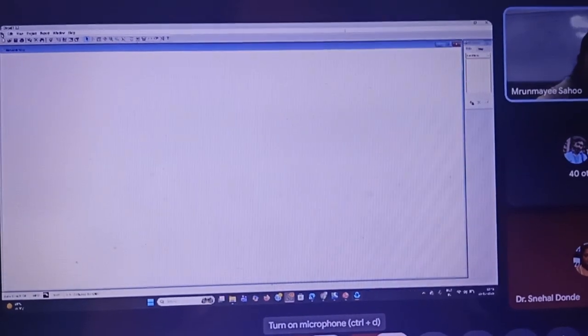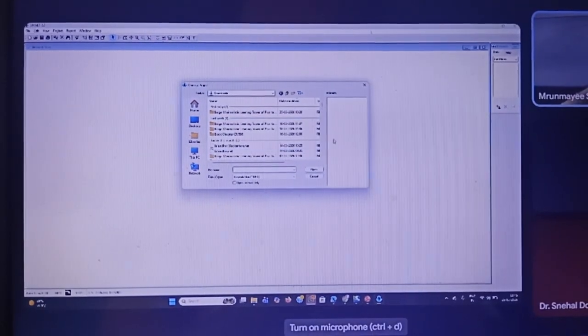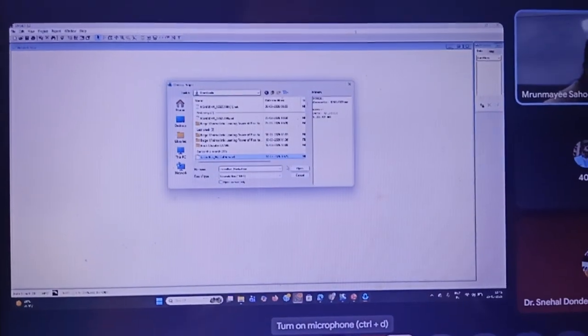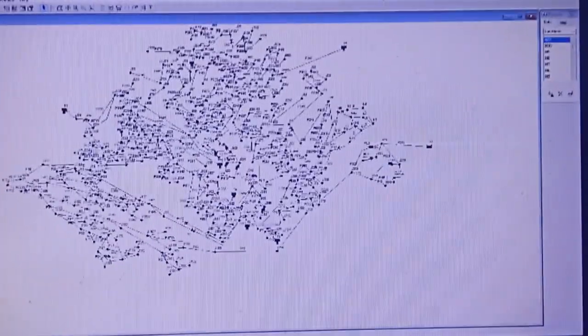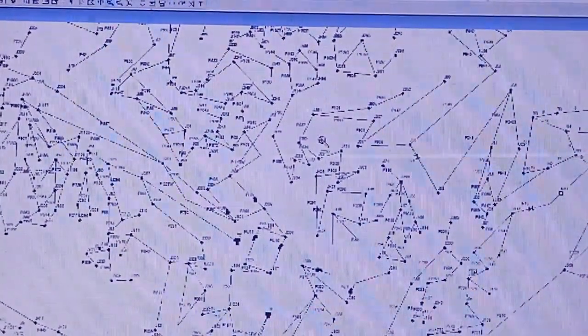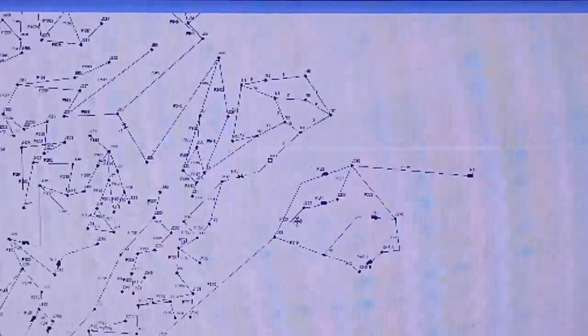Now, one of my students has recently done one system, which I will show you for Jalandhar only. You can see this is a system which is integrated with GIS. We have taken GIS data, and if I zoom in, you can see these are the pipelines. Here you can see we have pumps and tanks. These junctions are mostly the houses. Jalandhar is unplanned. At the same time, we are pumping the water from the reservoir. So this is my reservoir area.